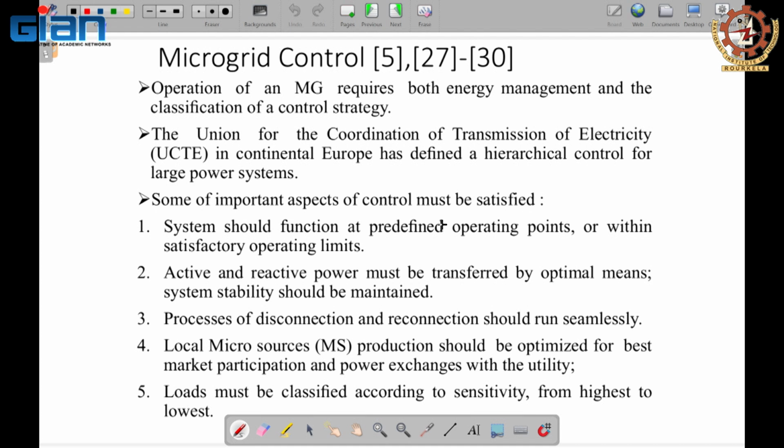A little bit of storage aside, electricity generation, active power and reactive power have to be balanced. A little plus or minus variation is acceptable within limits, but there should not be much variation between real power generation and consumption, and reactive power generation and consumption. Otherwise there will be symptoms and side effects, and the quality of supply will be affected.